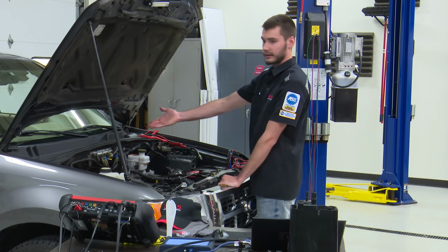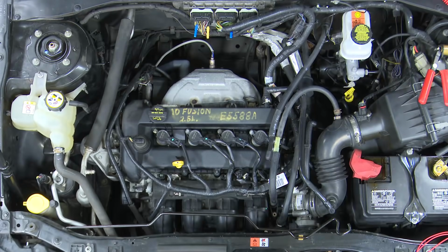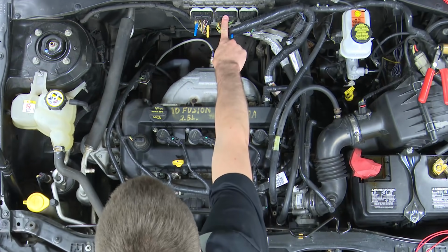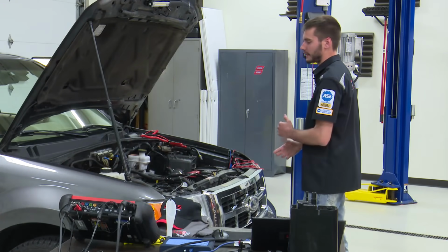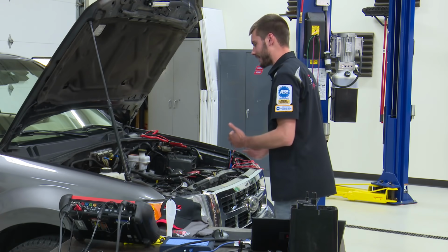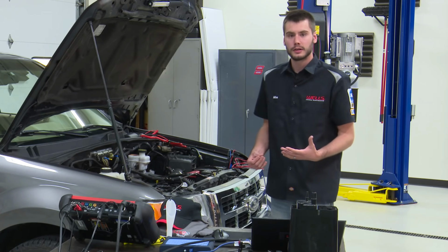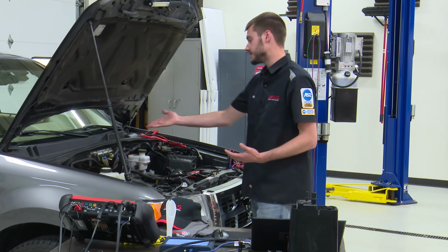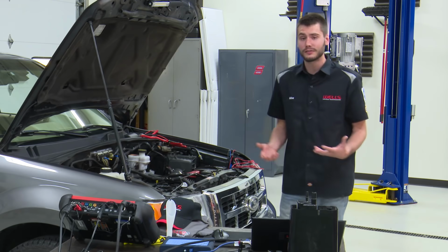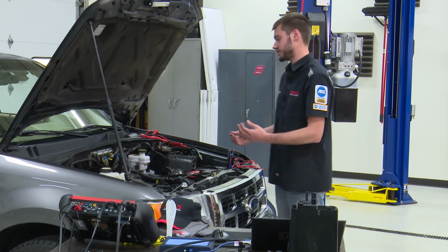At the back of the firewall here, you guys can see, oh, just ignore this, this was a used engine that I put in here. But our PCM is right back here. So instead of having to back probe at the fuel tank pressure sensor, the vent solenoid, the purge solenoid, instead of having to find all that stuff, I printed off a diagram, found my connections at the PCM, and back probed right there. Now, not every vehicle will be this easy. This one just happened to be.